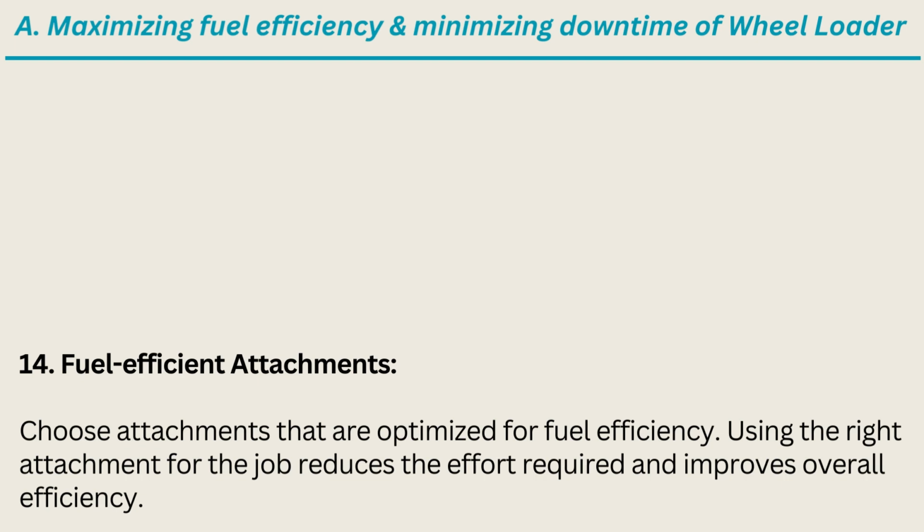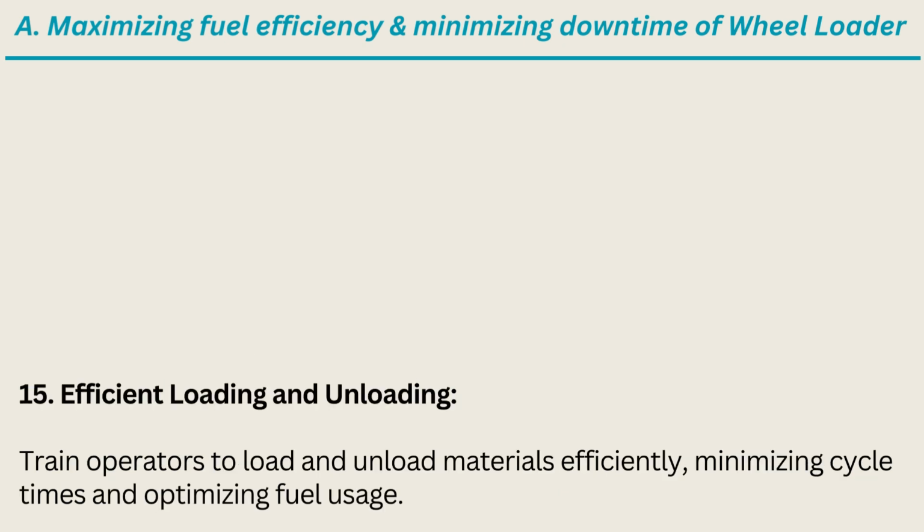14. Fuel-efficient attachments. Choose attachments that are optimized for fuel efficiency. Using the right attachment for the job reduces the effort required and improves overall efficiency. 15. Efficient loading and unloading. Train operators to load and unload materials efficiently, minimizing cycle times and optimizing fuel usage.